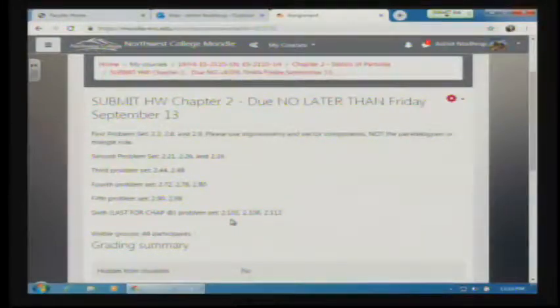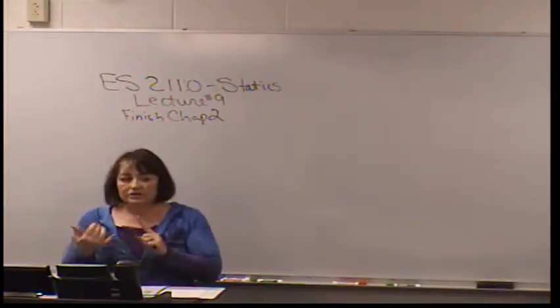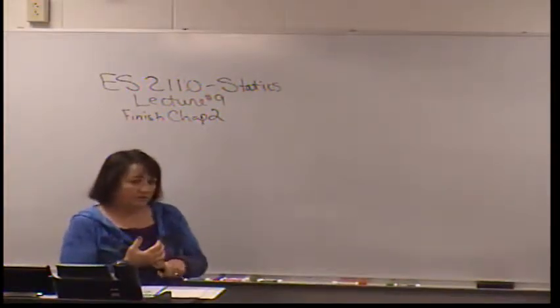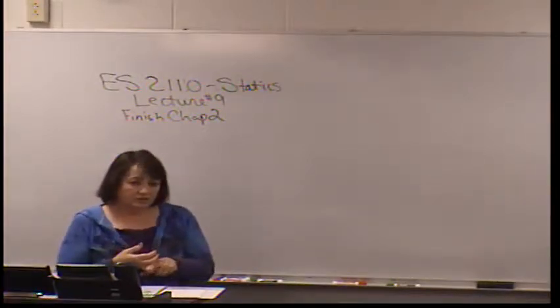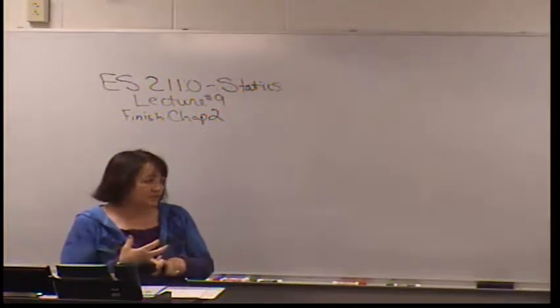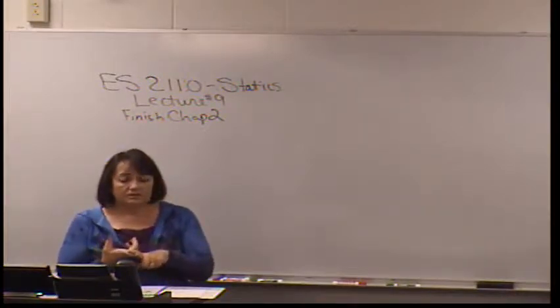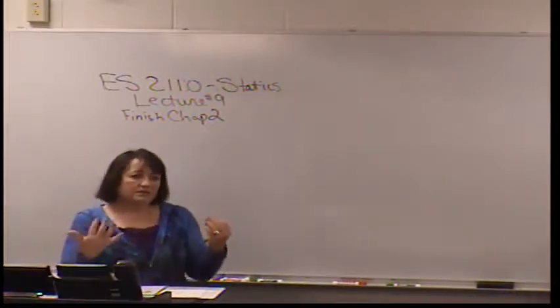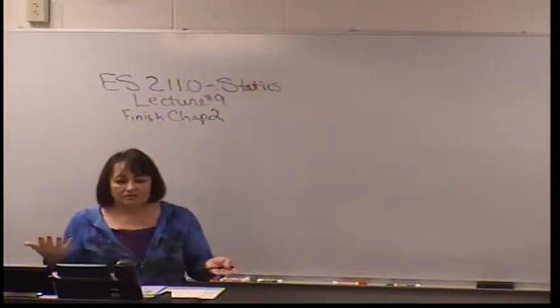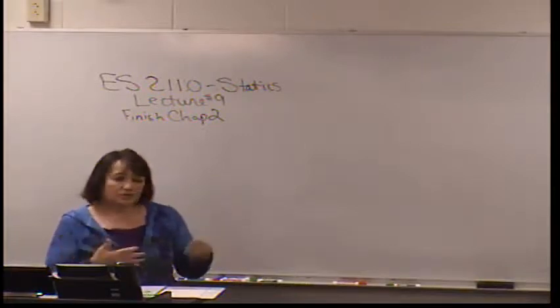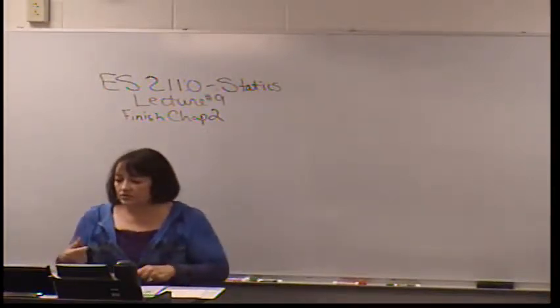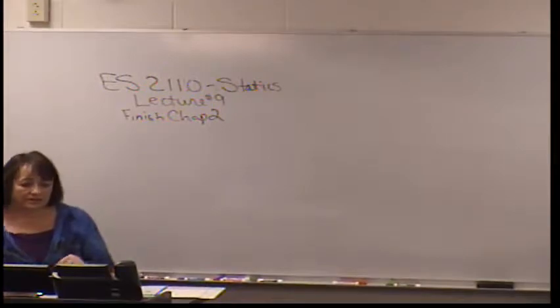So the steps that we're going to take, just like in the past: we're going to write out the problem and do a free body diagram. Then we're going to set up, instead of two equations, three equations: summation of forces x equals 0, summation of forces y equals 0, summation of forces z equals 0. Then we're going to start filling in the blanks, and we may have to solve equations simultaneously or do substitutions or whatever algebraic techniques will get us to answer all the questions in the problem.